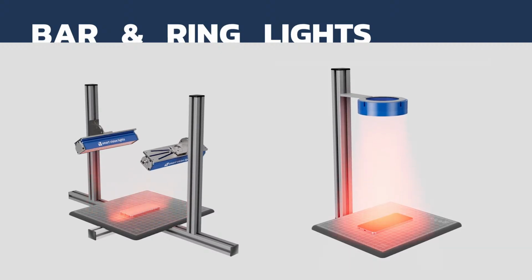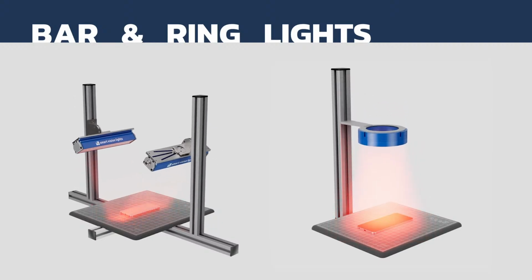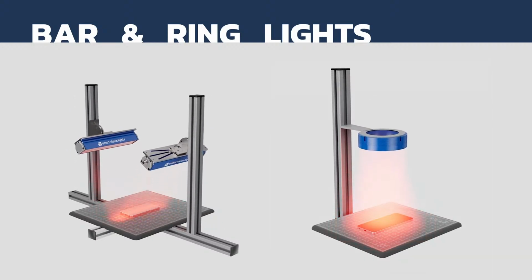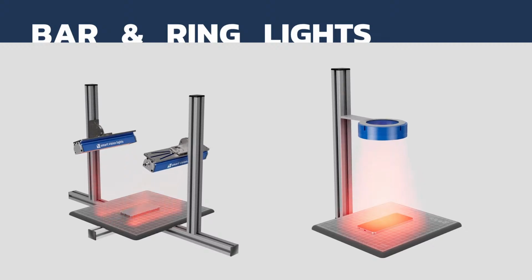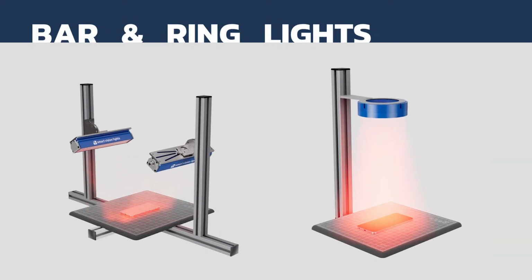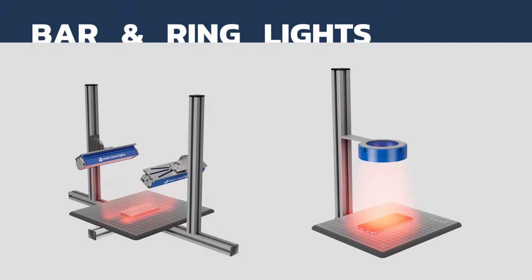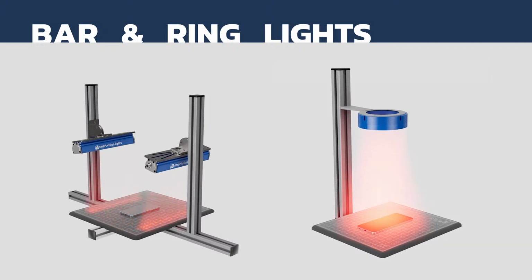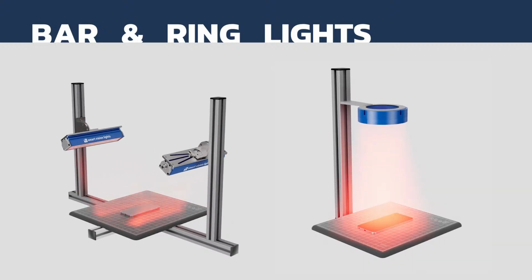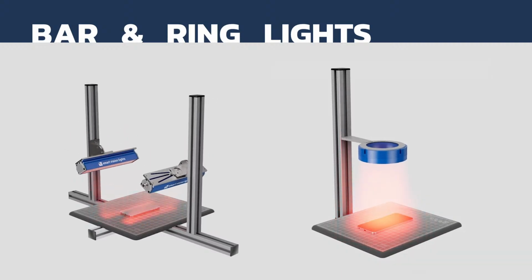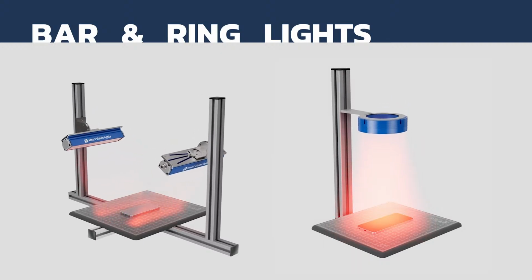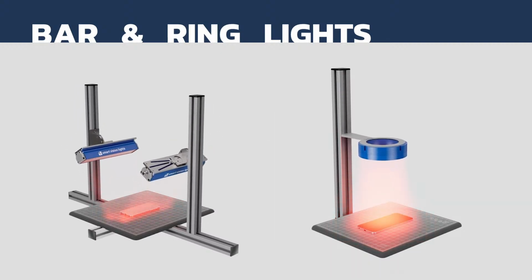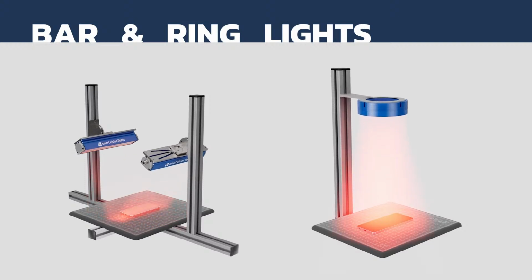The linear lights are also good choices, and often in machine vision, we can't look down that vertical axis. If we're over a conveyor belt or something, and there's automation moving in that area, sometimes we can't put cameras directly over center. And the linear lights are better for getting off to the side, especially if we have a side-mounted camera as well. And they offer more adjustability than the ring light as far as getting your overall height, your angle to the object, and your light working distance between the end of the light and the object correct.